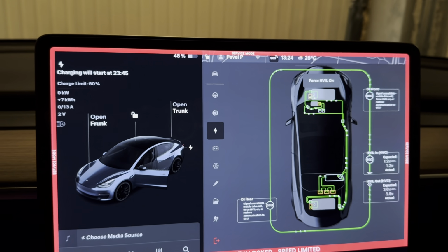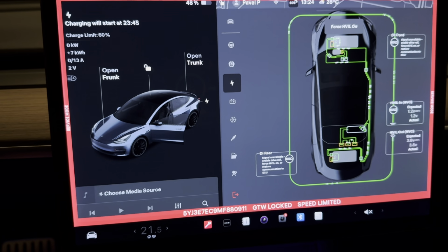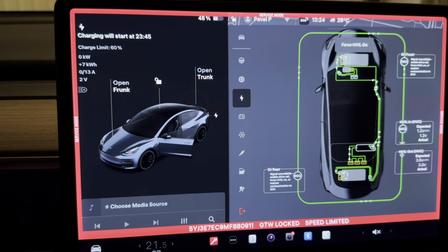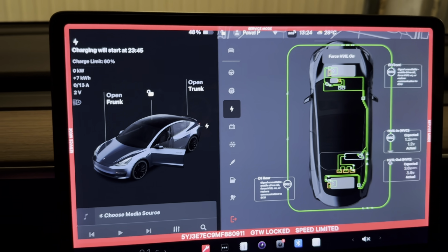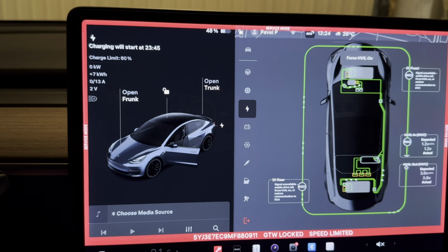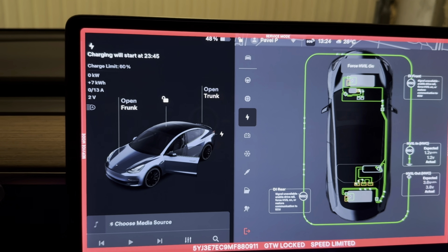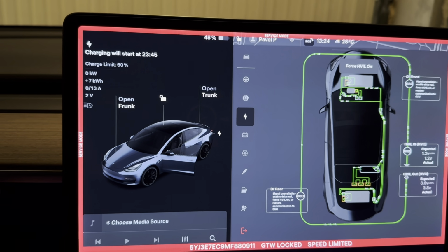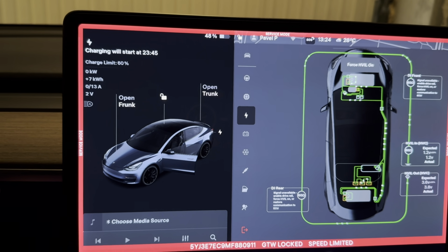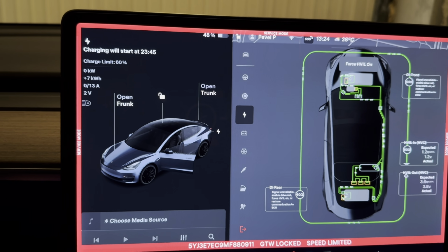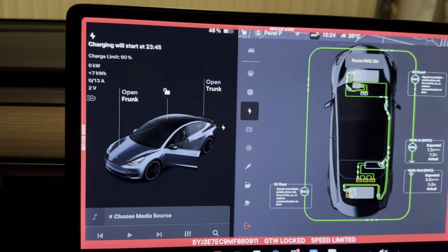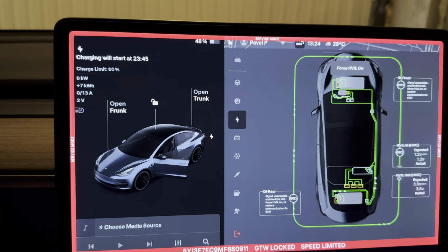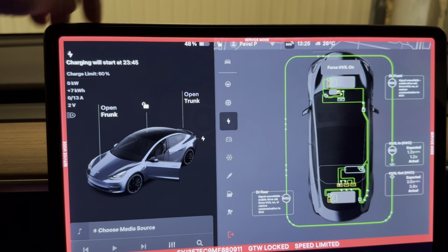For example, with the 12 volt, if you are sitting in the car and you touch any metal surface, you're basically connected to the negative of the 12 volt battery. And if you touch, let's say, the positive terminal of the battery, you will complete the circuit, but because it's too low a voltage, no current will flow through you and you will not be fried. But that's not the case with the high voltages in the high voltage system. So that's why the battery doesn't use the car chassis for ground, and it's a so-called floating type of circuit, and this is representing the complete circuit.